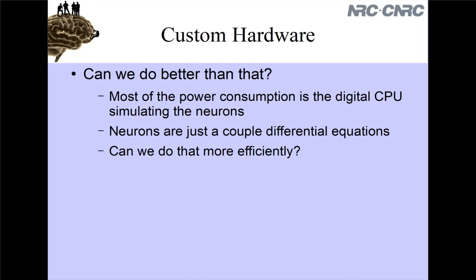One of the arguments there is, look, this whole idea that computers are all just ones and zeros, ones and zeros don't exist. All there is is voltages. And there are just a lot of mechanisms in computing that make sure that things near a voltage that they define as zero end up staying at zero, and things that are near one end up staying at one. And it turns out that something on the order of 90-95% of the power consumption is about keeping the zeros at zero and the ones at one. It's keeping these nice clean signals such that the rest of the computation can actually work. It's because we've gone ahead and designed everything to be digital.